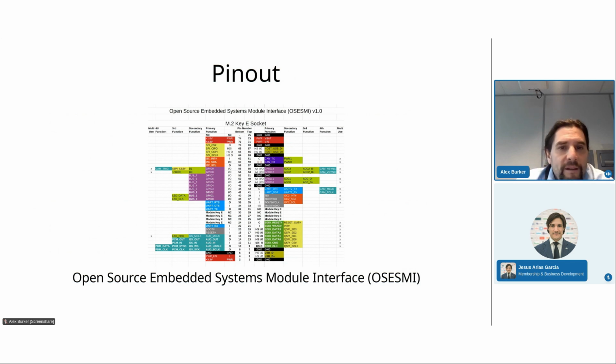There are the standards you need. You have an 8-bit parallel bus, SPI, I2C, and I2S, so you basically get everything you need for an embedded device. You also get two serial ports, CAN, and USB. That's important because USB is coming more and more. So I really tried to cram in everything that could possibly be needed.